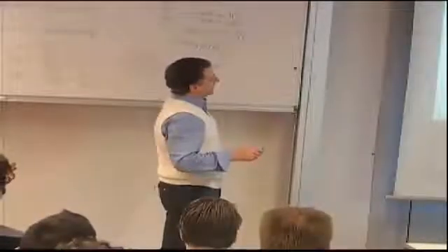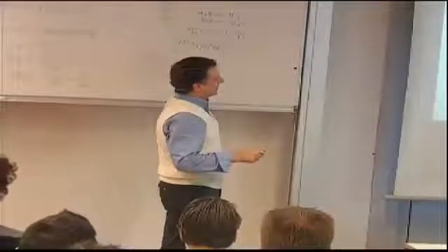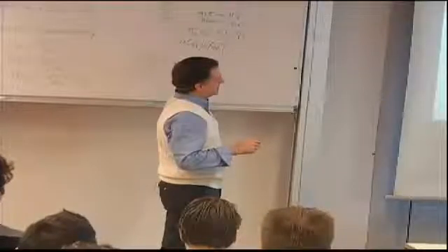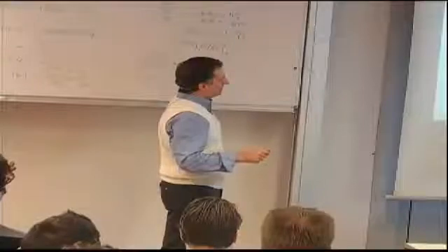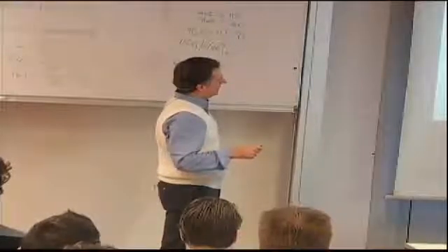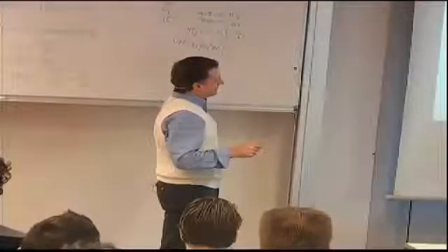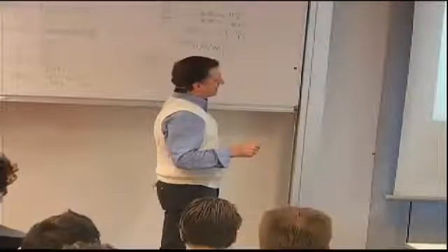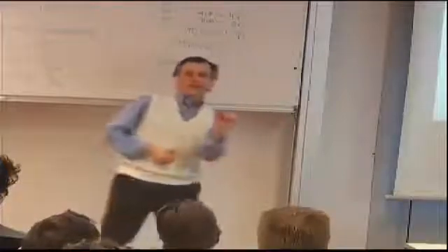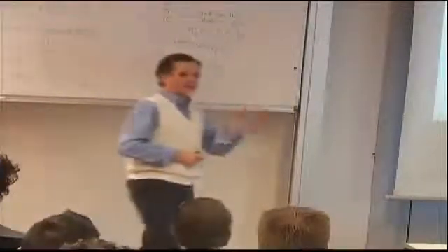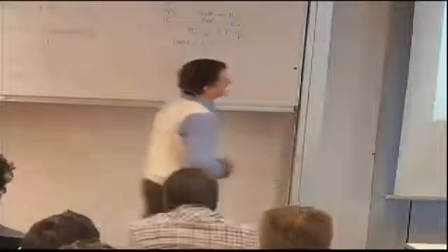And this is one of the cases where you can solve it exactly using infinite series. The boundary conditions for the problem tell us that at this top surface, x equals 0, my sigma x stress is 0 everywhere except for the middle point location, where it will actually equal my applied force divided by the local cross-sectional area, h the thickness of the plate, and little h the width of the region, let's say of the flange of the stiffener, or the width over which this load is applied.